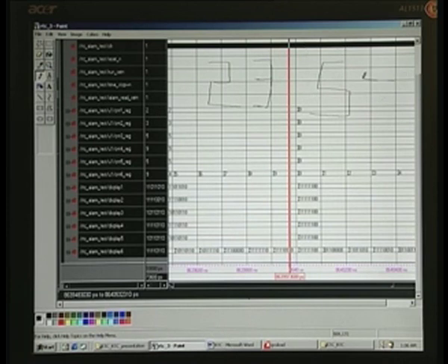And now for 9, so what you have here is you do not have this, this is C, D, E, E is 0. So let us make sure about cross check at display 4. So this is A, B, C, D, E, this alone is 0. Just do not be confused about this 0 because this is only for decimal point. Anyway, we are not turning on the decimal point, that is why all of them are 0.